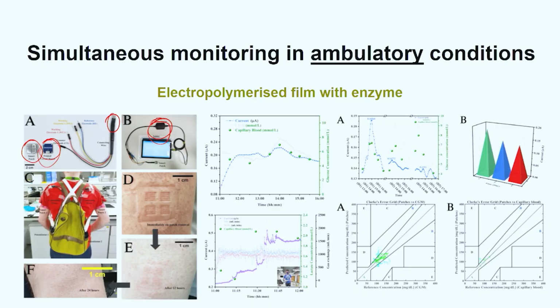And we also needed to use these commercially available ones, because I mentioned this project was about simultaneous monitoring of glucose and lactate. What that means is you should be able to use the same potentiostat in a multi-channel format and measure glucose and lactate from the same device, but you could never get more than one channel running at a time. That is a big problem. So we ended up having 2 devices. That's why we needed this bag here, and you can see there's one potentiostat on this side, one potentiostat on this side, one sensor here, one sensor here. Poor me, you can imagine.